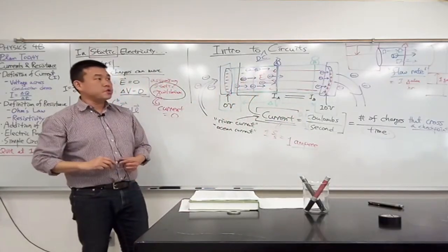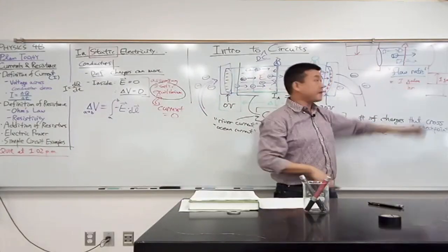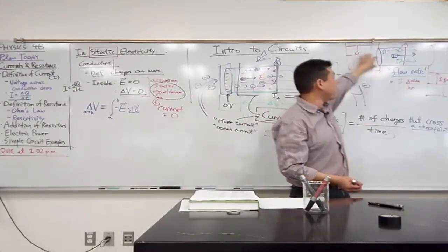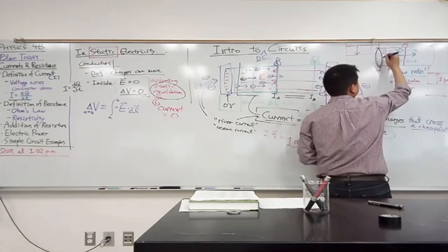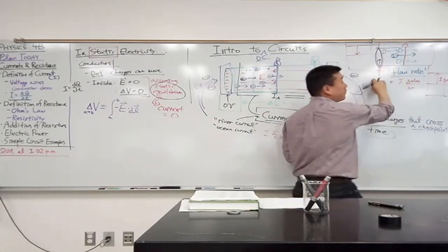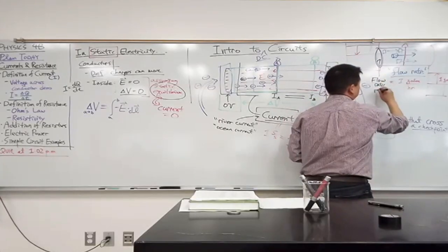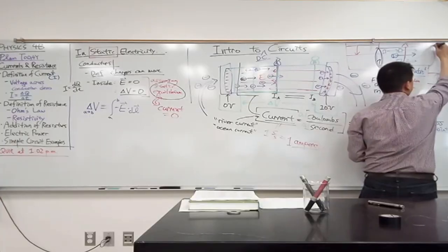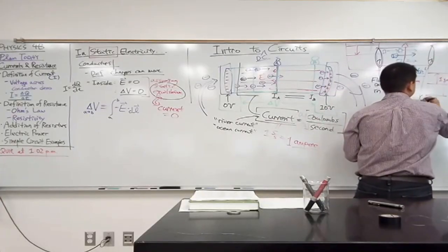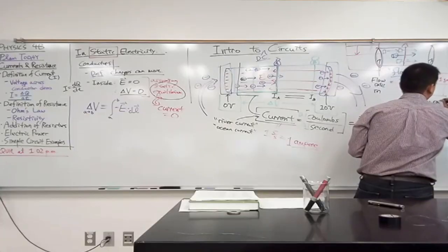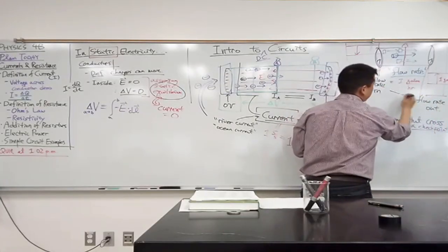If you don't have that intuition, I want you to fall back to this model here. So let's say you can measure the flow rate of the water here at two different points. You could measure it here, see how much water is entering. Let me call that flow rate in. Or you can measure it here, how much water is leaving the volume, flow rate out. So hopefully more of you have the intuition that this flow rate in and out should be equal.